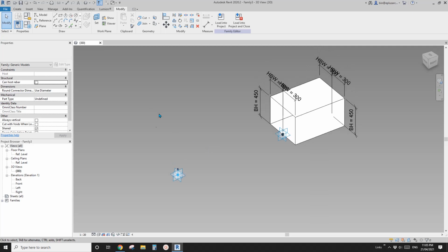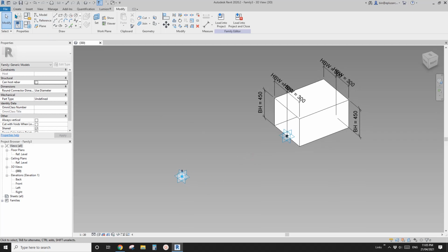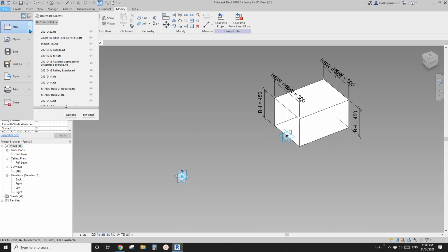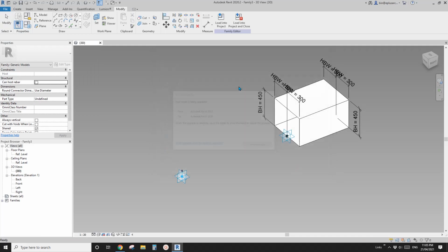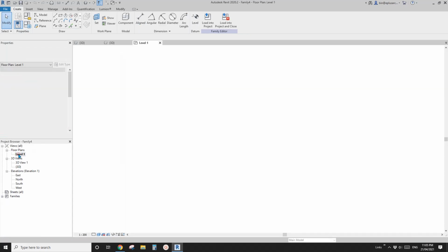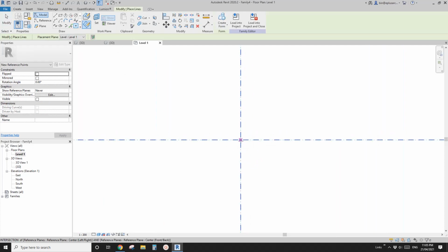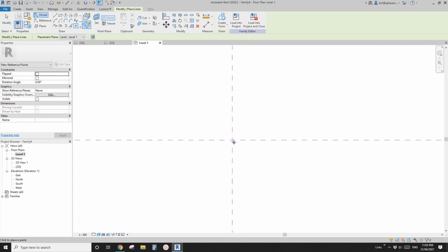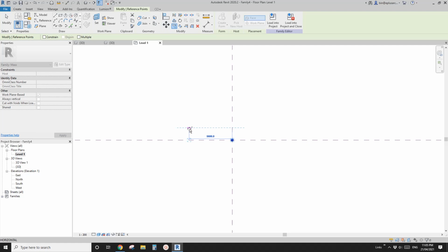Let's model the mass. Okay, I'll show you. We need another step here, but before that, let's create the mass. Let's go to floor plan. I'm going to make a small one, so my computer will run faster. Place one point and copy it, let's make it small, maybe 5 meter. Okay, and another one here, 5 meter as well.